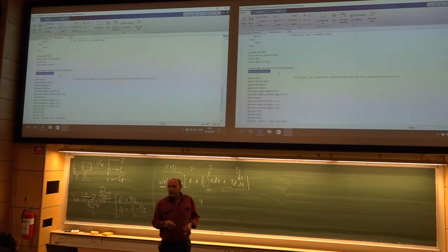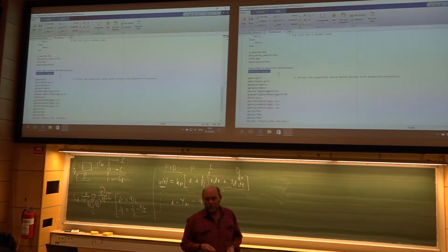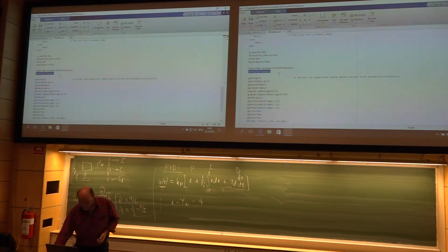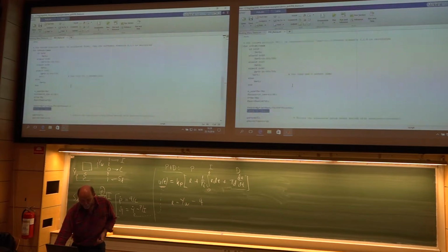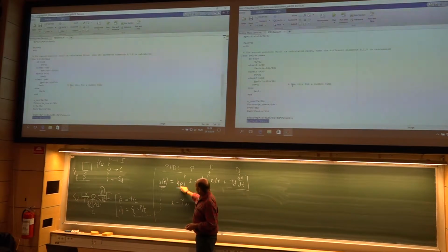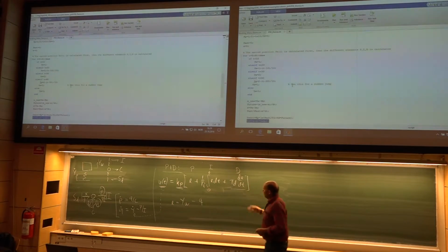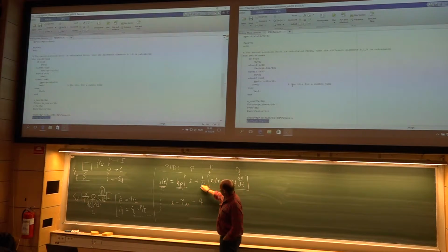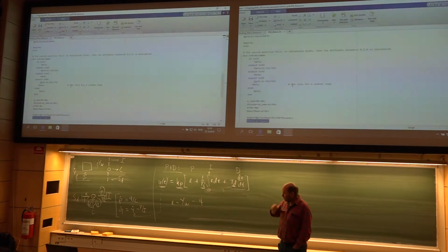Any questions to the source code? Okay. Then you have 3 parameters you can play around with. The proportional constant actually influencing all 3 terms, and then you have these 2 time constants here that then have to be specified.